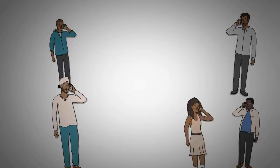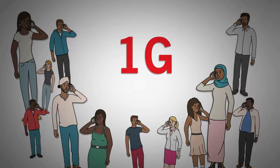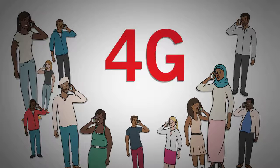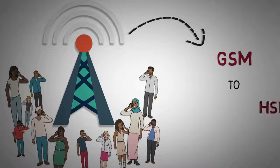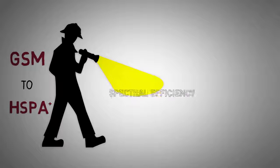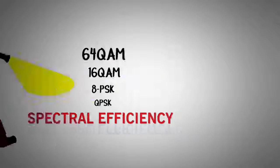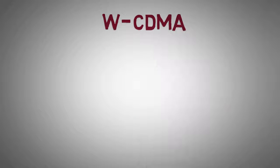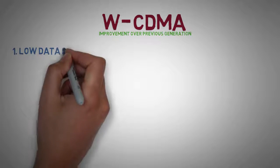As the number of users and their demand started growing, communication networks evolved from 1G to 4G. Radio part was significantly enhanced from GSM to HSPA+. Now, focus was shifted towards better spectral efficiency by using higher modulation order like QPSK, 8PSK, 16QAM, 64QAM, etc. WCDMA improved upon some of the problems of earlier generations like, first, low data rates.